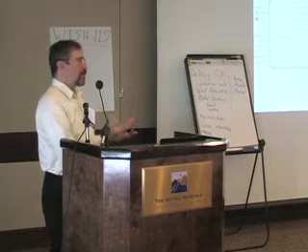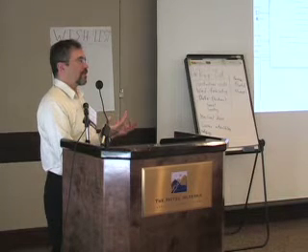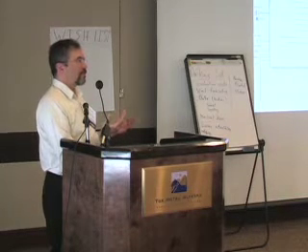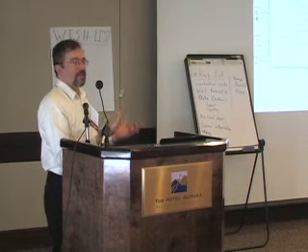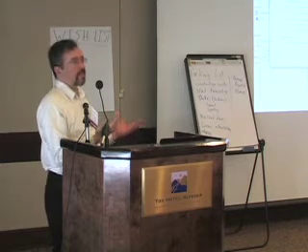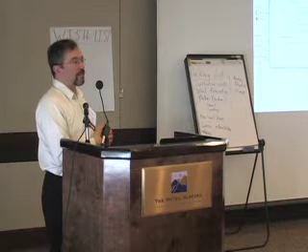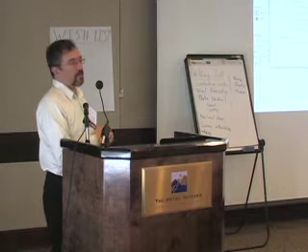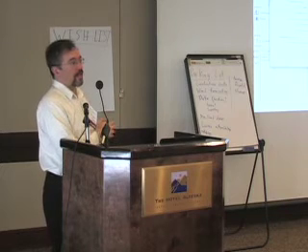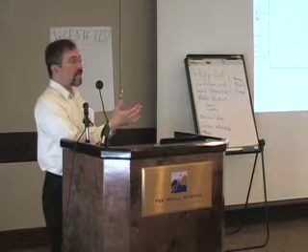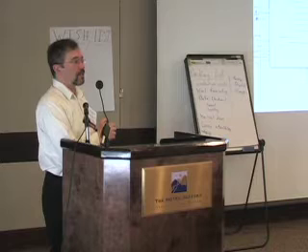But if you're not a big interconnected utility and you only have a couple of generators, if you lose one of those, I don't know what happens. You probably have a temporary outage because it may not be practical, if you only have 2 or 3 generators, to maintain that N-1 contingency.